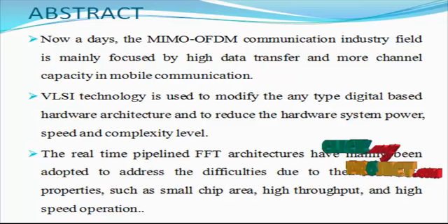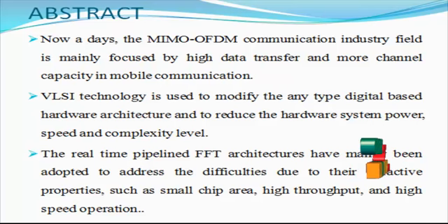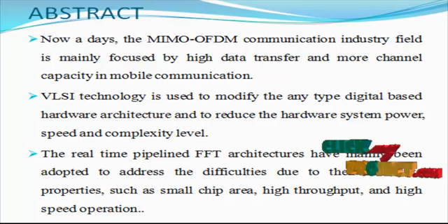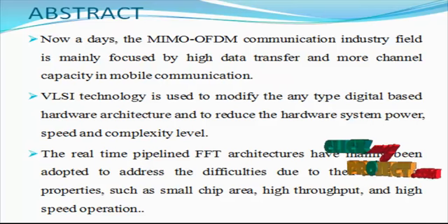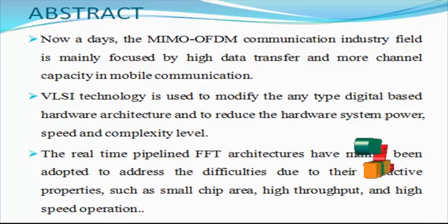We present an efficient combined single path delay commutator, delay feedback Radix-2 pipelined fast Fourier transform architecture, which includes log2 n minus 1 SDC stages and 1 SDF stage. The SDC stage processing engine is proposed to achieve 100% hardware resource utilization by sharing the common arithmetic resources with a time multiplexed approach, including both adder and multiplier. Thus, the required number of complex multipliers is reduced to log4 of n.